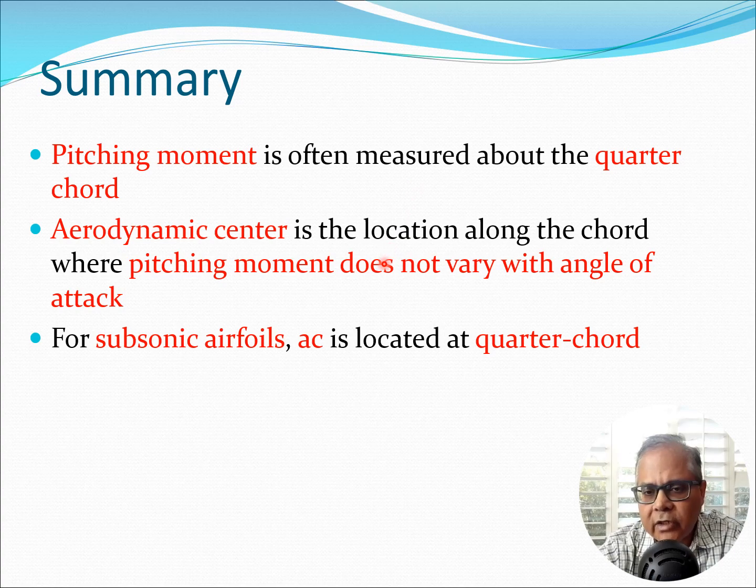We also saw that there is a certain point known as the aerodynamic center, and if you take the pitching moment about the aerodynamic center, then it does not vary with the angle of attack. We also see that for a subsonic airfoil, the aerodynamic center is located at the quarter chord. So this is something which will often simplify our life dramatically. If we are in supersonic situations, the aerodynamic center moves back to the mid chord region. That's something we'll probably look at later in this class.